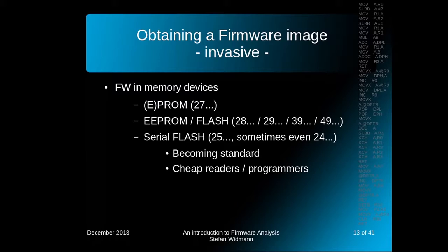But very nice to see is that serial flashes, those 8-pin devices, 25, sometimes 24, are more and more becoming a standard. And they are easy to desolder, they are easy to resolder, and there are very cheap readers and programmers available. But please, even if some say we can do it in system without desoldering the chip, please don't do it. It can lead to very big problems.